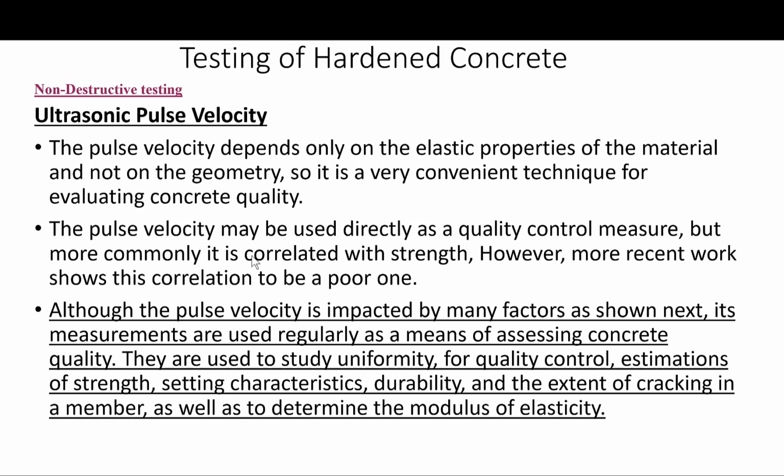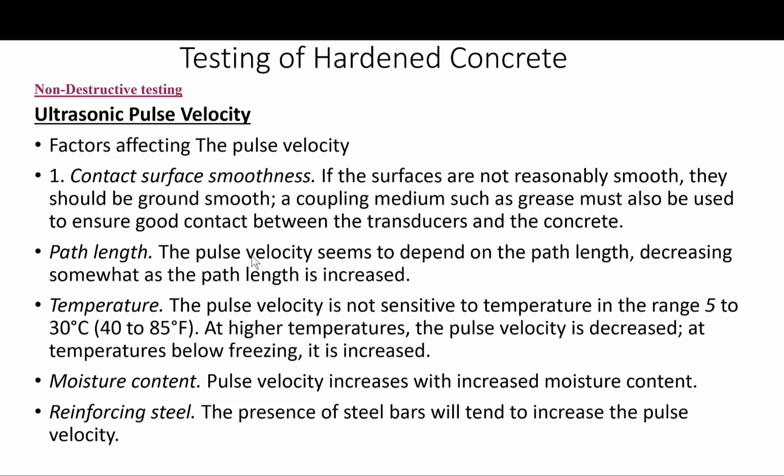As with everything else, pulse velocity is affected by a number of factors. First, the contact surface smoothness. If the surfaces are not reasonably smooth, they should be ground smooth. A coupling medium such as grease must also be used to ensure good contact between the transducers and the concrete.